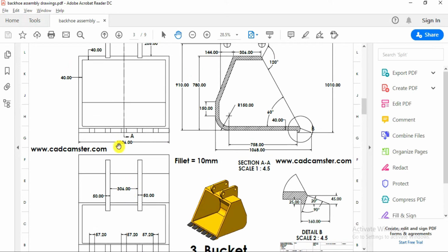So for that you can see we have to first subtract 306 mm from 1006 mm, which is 700 mm, which divided by 2 gives 350 mm. Means this section is 350 mm from both the sides. Each of them are 350 mm apart.